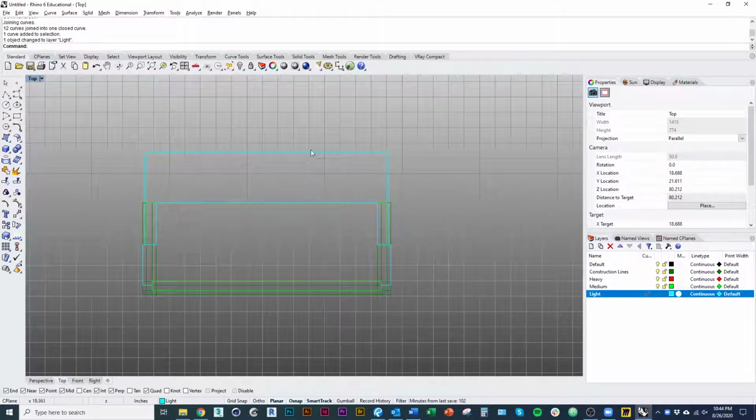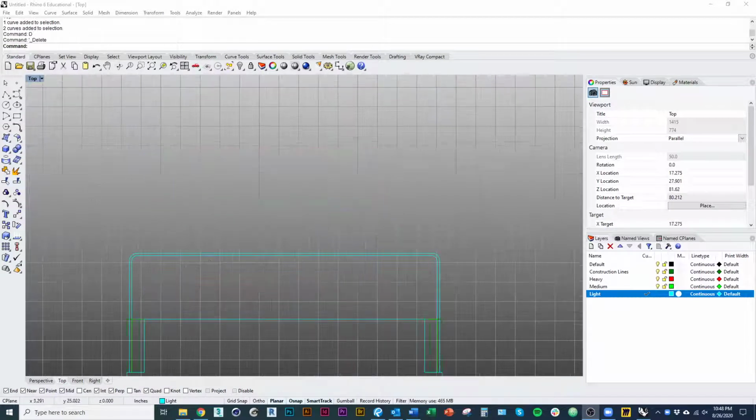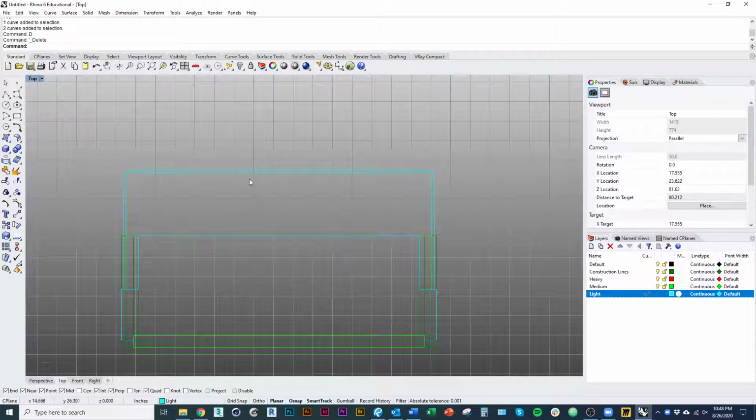Now the other thing that I need to do is put that little handle here. Okay, so the way we're going to draw that spiral in the handle is we're actually going to draw it in 3D and then bring it down into 2D. So rather than messing around with working between projections, because we're in Rhino, we can just draw a 3-dimensional spiral, and then we can use that to show it in 2D.